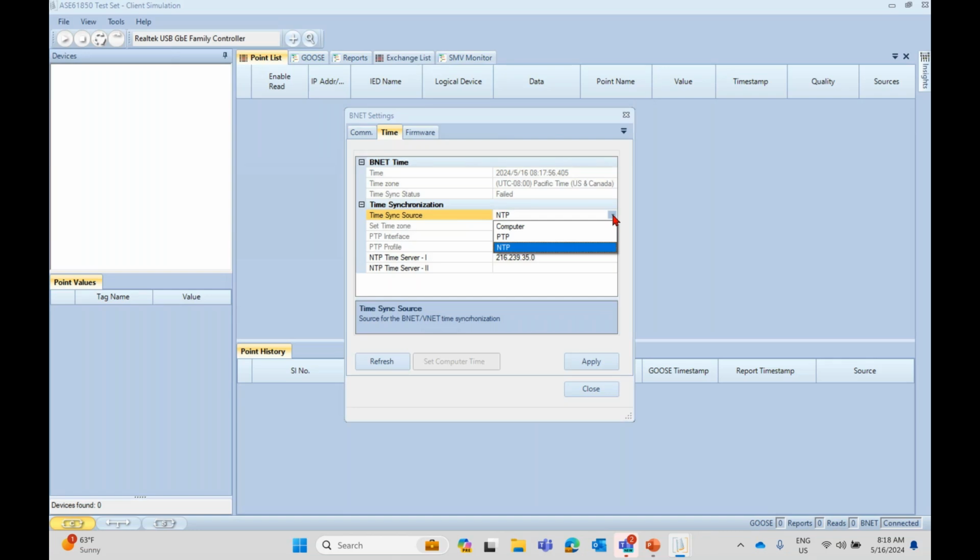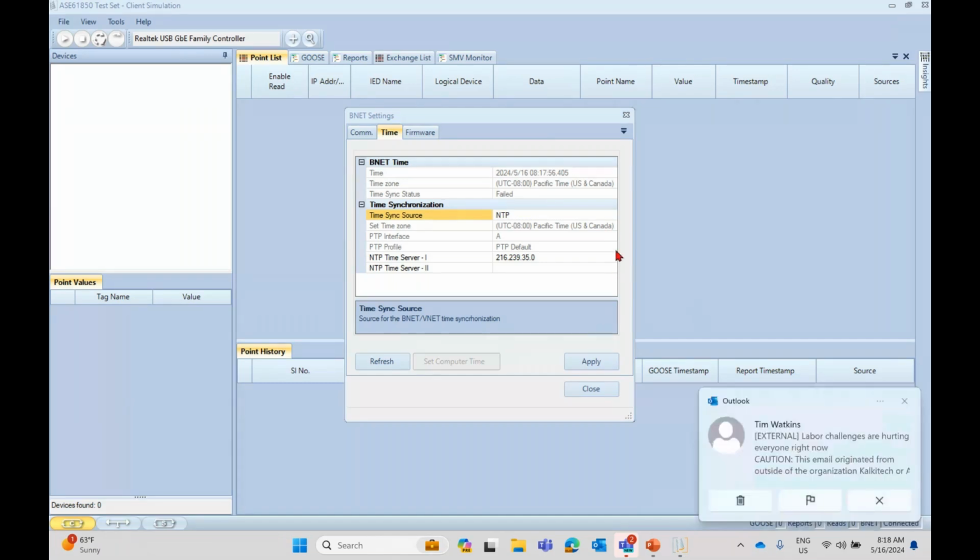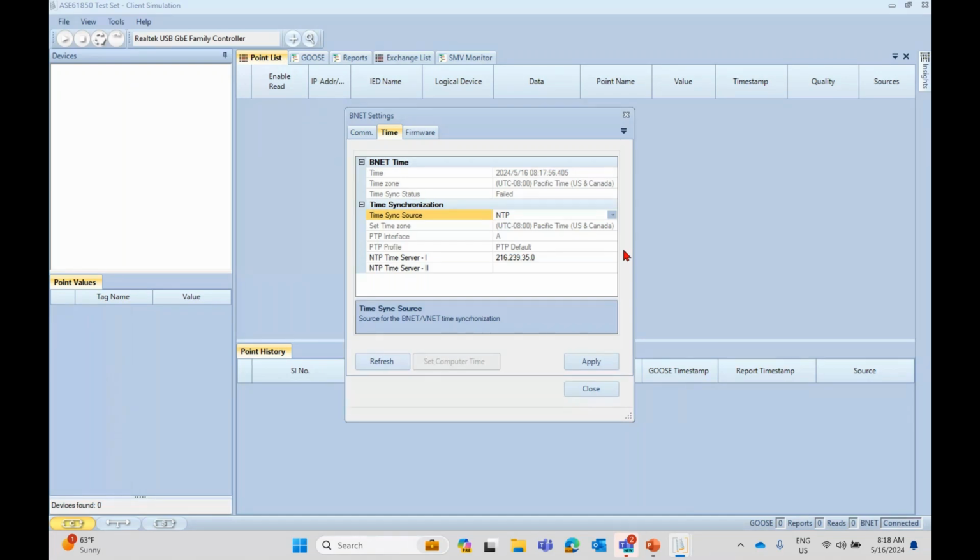Yeah, the process bus communication in general depends highly on time synchronization, and it's not only the time sync part, it is the very high accuracy of time sync that is required for the process bus, because all the process packets or sample value packets don't carry the timestamp by default in most cases. So there is a sample count parameter that is shared, but because of that, all the devices in the network are expected to have a very accurate time source, so that everybody is on the same page with respect to the time.